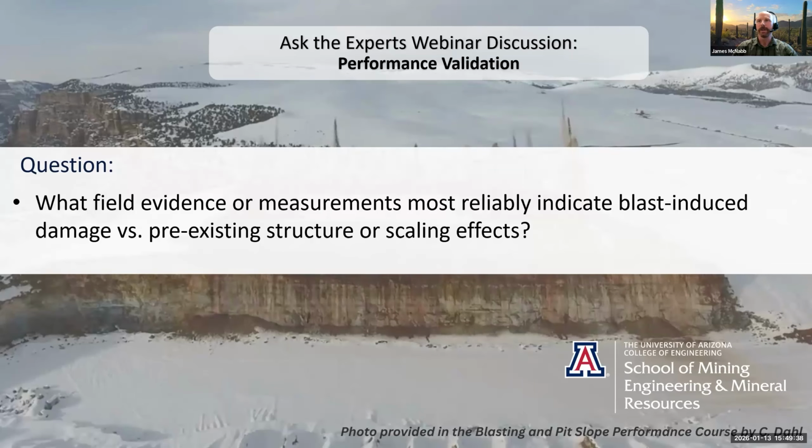Yeah, so some of your first and most obvious ones that we have to look for in the field after excavation has happened, or even before, are irregular cracking, non-conformance along the crest line, irregularities along the crest line, just unevenness, loose rock, a jumbled, shattered look that's not consistent with the geology, and cracking that's in proximity to the blast itself.